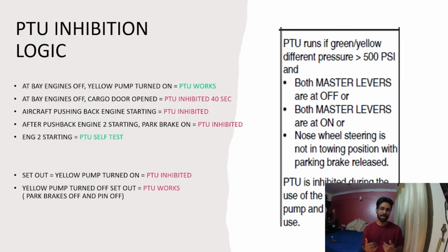Now suppose I only started one engine, I am doing a single engine taxi out. And I am taxiing out as per the single engine procedure, which is a different procedure, you don't have to worry. We will turn on the yellow electric pump.